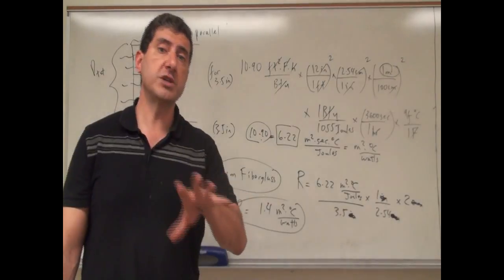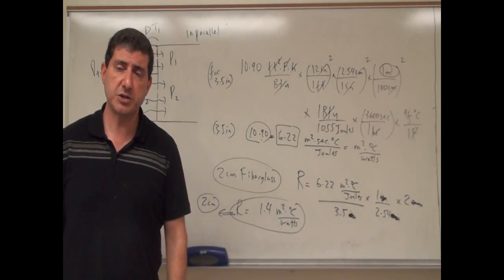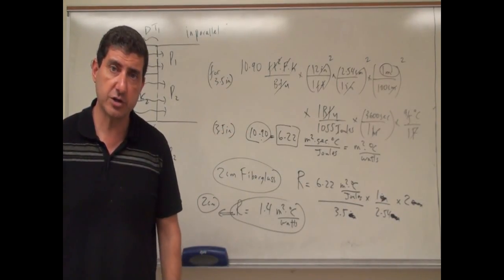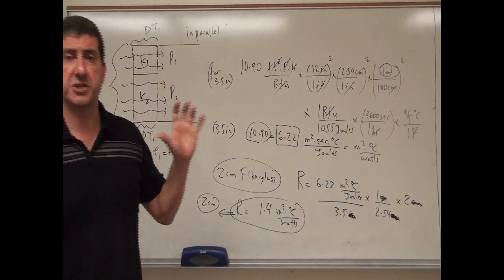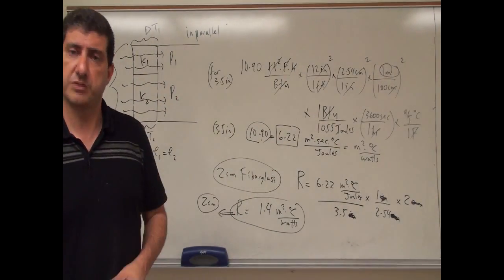So now this gives you a good example of how to add up resistors in series and parallel, how to express the answer in the insulation factor, and then how to convert from the insulation factor of building materials to the metric unit system. And thank you very much.